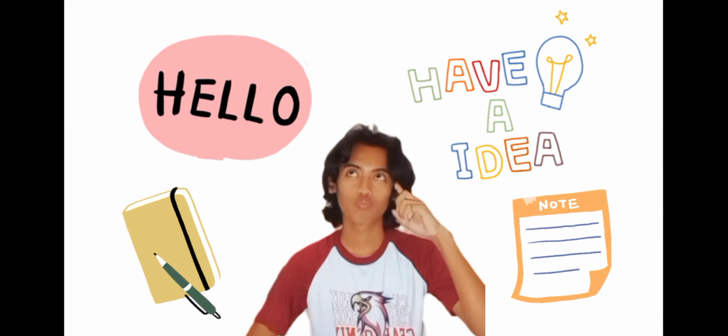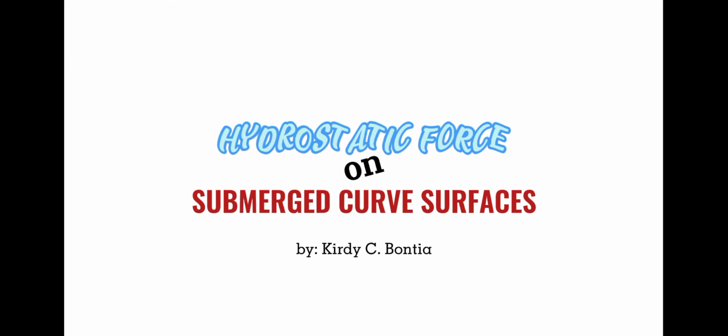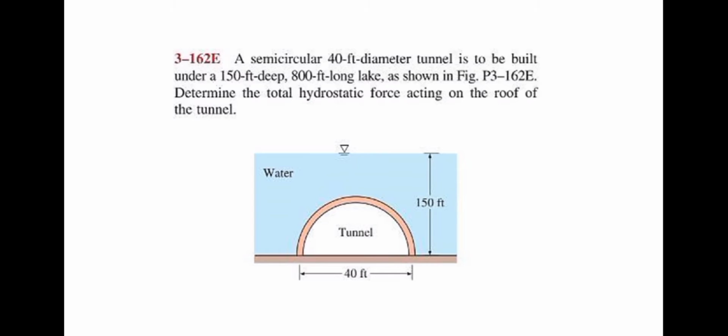Hello, today let us solve some simple problems about hydrostatic force on submerged curved surfaces. So here's the problem. A semicircular 40 feet diameter tunnel is to be built under a 150 feet deep, 800 feet long lake as shown in the figure. Determine the total hydrostatic force acting on the roof of the tunnel.